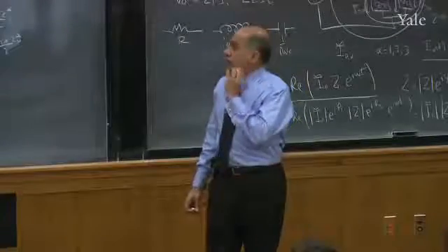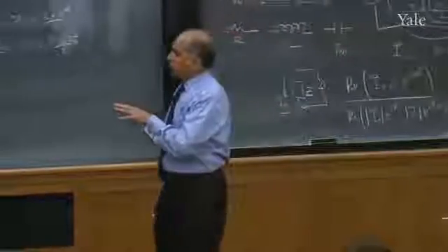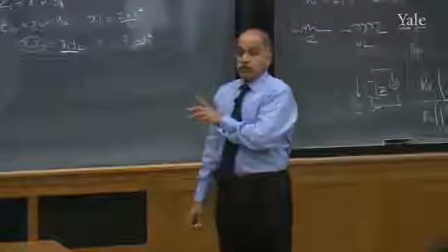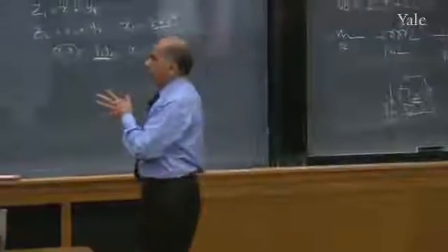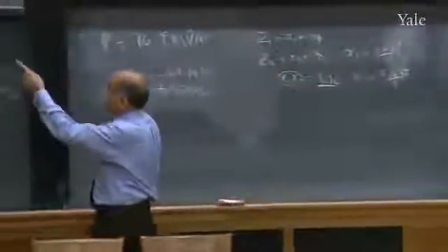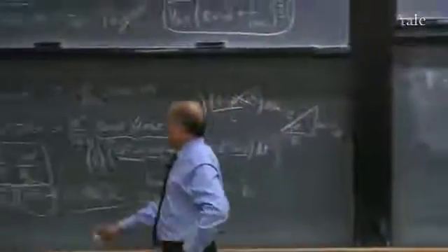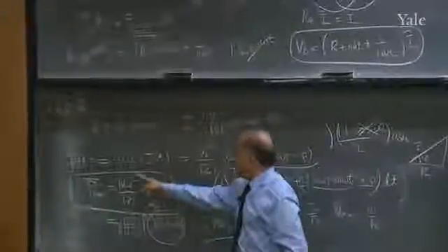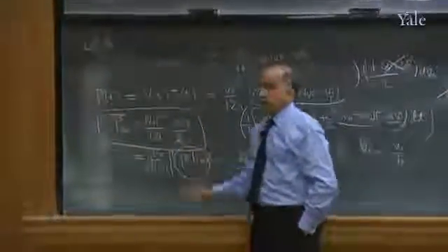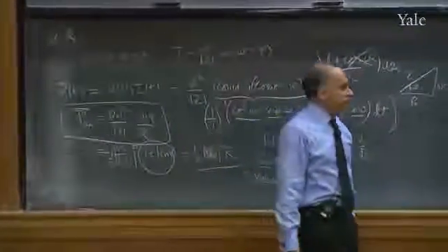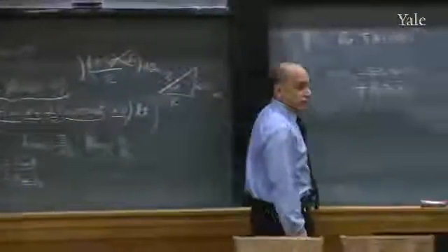Therefore, I tell you that when you do these AC circuits, when it comes to power, forget any of the gimmicks you learned. You'll usually be asked to find the power only for an LCR circuit, the single loop like that. Then just go back to this one. It's just I square R written in this language. And cosine phi is called the power factor.